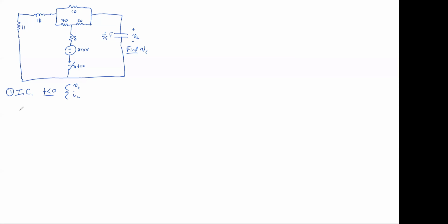So let's see. Sabine, I've got you next. Guide me through redrawing this thing. So the first part is that the switch is going to be closed and your inductors are going to be shorts. And your capacitors are going to be opens. Perfect. So that gives us this.